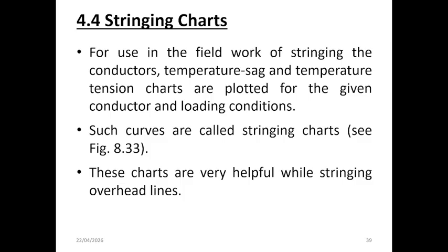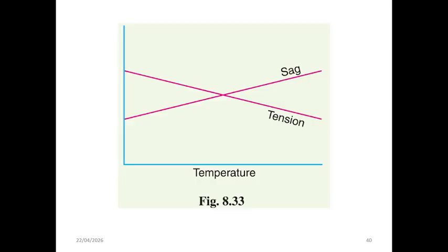By using this chart, you can ensure that the conductor is installed with accurate mechanical properties, avoiding excessive tension or unsafe sag conditions and so on. Therefore, stringing charts play a crucial role in ensuring the correct and safe erection of overhead transmission lines in real-world conditions.